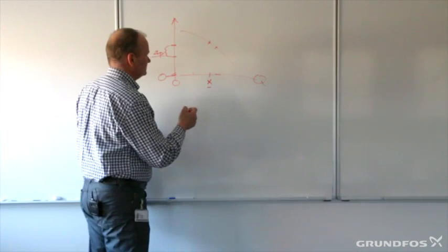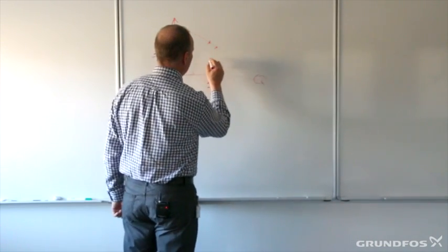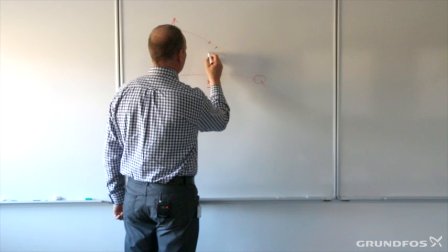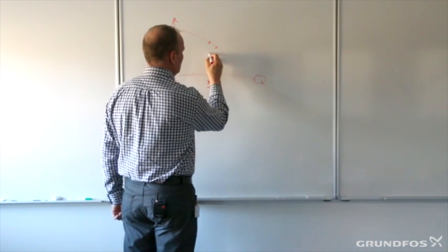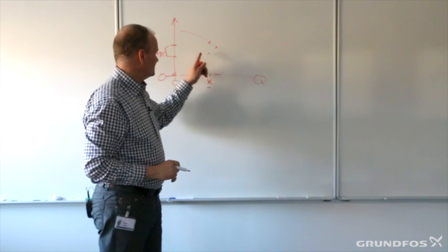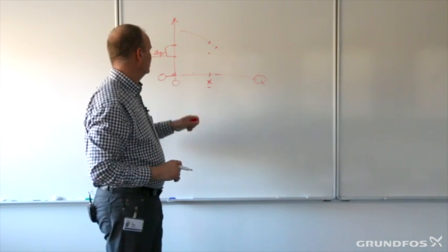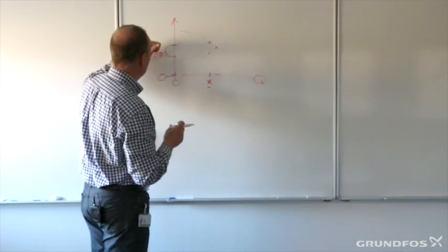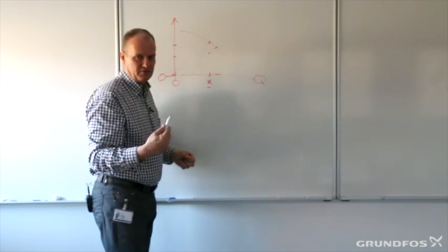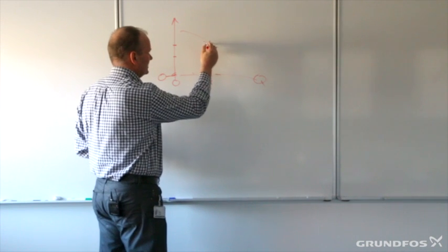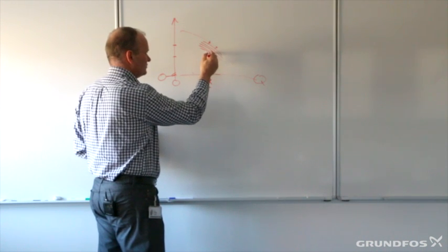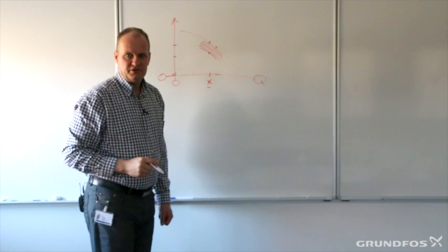So what we do is that if we have this need here and we know that we have a system characteristic which is determining that we need this pressure according to this flow here, what we actually do is that we are still telling the pump to operate with a constant curve, but then we are just adjusting the curve downwards until we reach this duty point here.